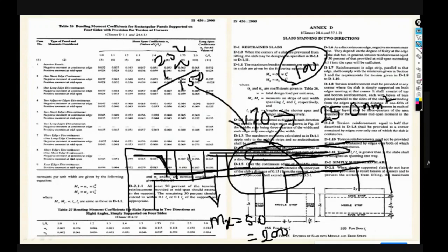So why have they replaced it? If we see the diameter of bar required for the slab as well as the beam, generally we provide a larger number and diameter of bars in the beam as compared to the slab. In a slab, 8 mm or 10 mm is sufficient, basically 8 mm, but for a beam generally we go for 20 mm, 16 mm. So it is very difficult to bend them at the proper position or in the proper manner. That is why only for the beam we replace it with the extra reinforcement.